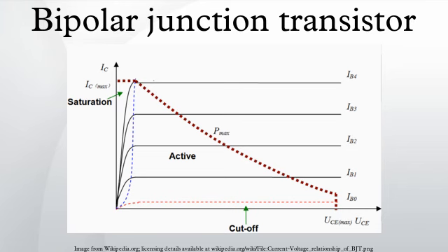However, to accurately and reliably design production BJT circuits, the voltage control model is required. The voltage control model requires an exponential function to be taken into account, but when it is linearized such that the transistor can be modeled as a transconductance, as in the Ebers-Moll model, design for circuits such as differential amplifiers again becomes a mostly linear problem, so the voltage control view is often preferred.